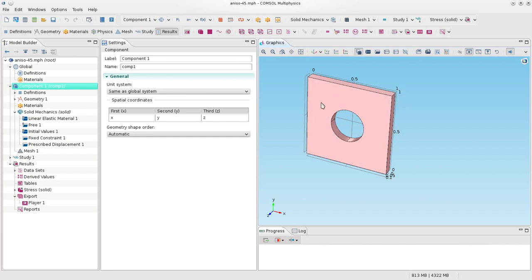So it's as if this is metal, and as in an earlier example that we used, for instance, in the case of thermoelasticity, it's as if I put a strong magnet here, and that magnet allows the plate to slide freely on it, but when I pull on the magnet, it makes the plate move with it. And because the magnet is rigid, all the points are going to get displaced by the same amount along the x direction. So that's the constraint.